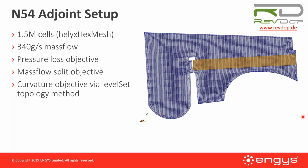This particular case, it was 1.5 million cells that were meshed with HELYX hex mesh, so done within the GUI. The mass flow rate was about 340 grams per second. The two objectives were pressure loss and mass flow split between those two outlets. And then also a curvature objective was applied to the level set equation to increase the manufacturability of the final